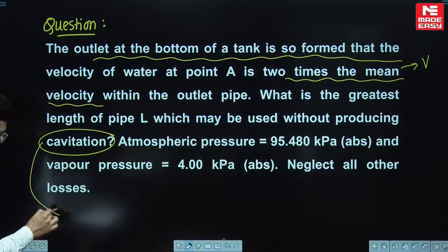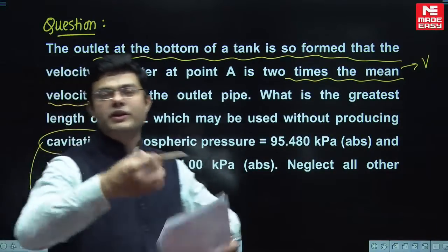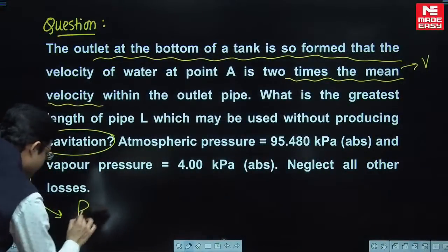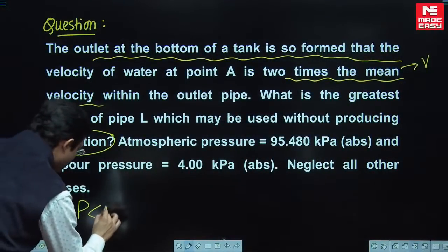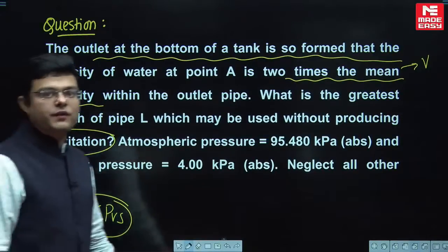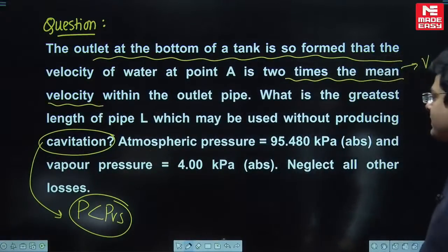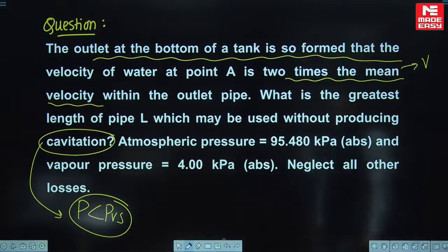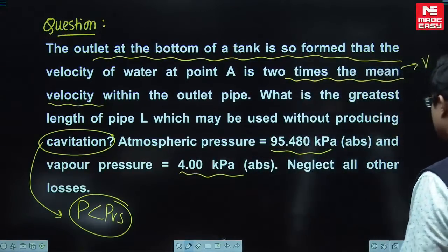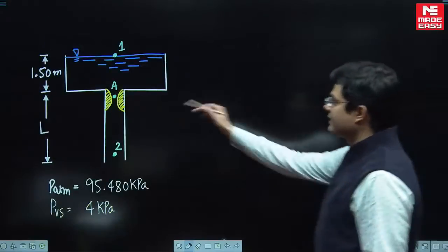Now how many of you know when the cavitation is going to take place? Cavitation is going to take place whenever the pressure of the fluid falls below the saturated pressure. Atmospheric pressure is also given, vapor pressure is also given, and yes, this is the diagram.